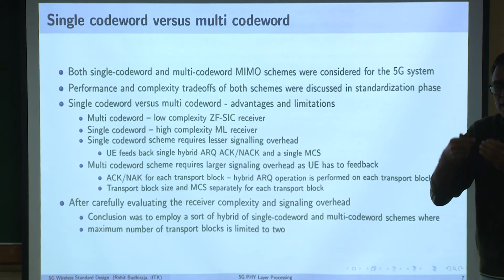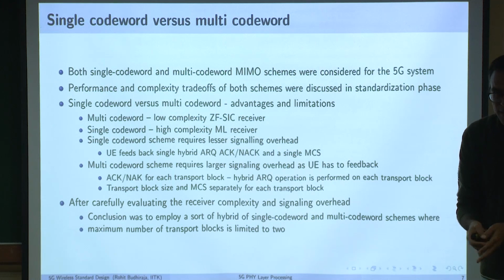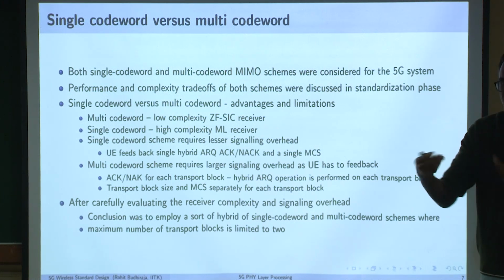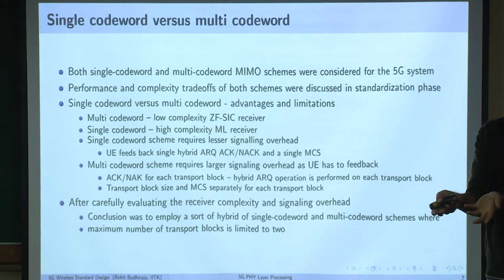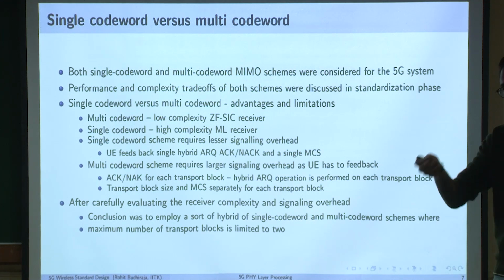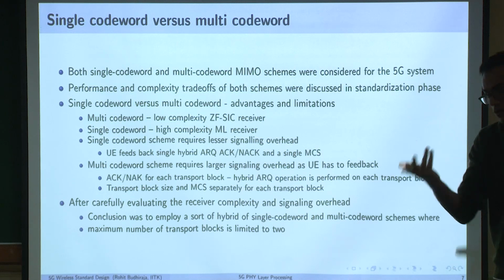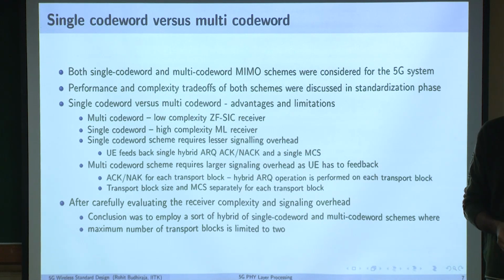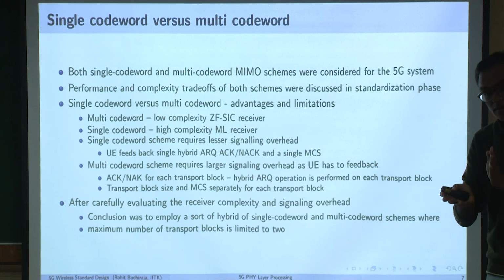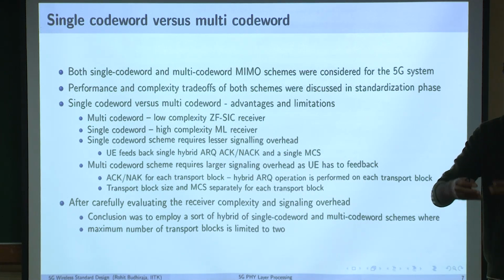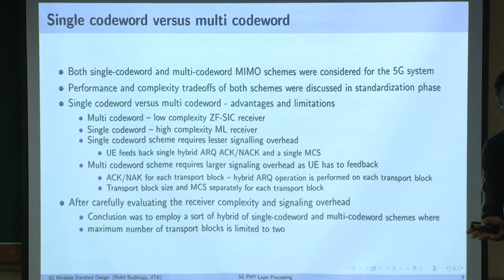Then even though the signaling overhead is high, you don't mind, because UE is observing a good channel. So even if it is anyway going to get a high data rate, even if the signaling overhead is high, you will have to support that. Because if the rank is up to 8, it essentially means a very good channel. When the rank is up to 4, compared with it, it is a degraded channel, even though in isolation that itself is good.